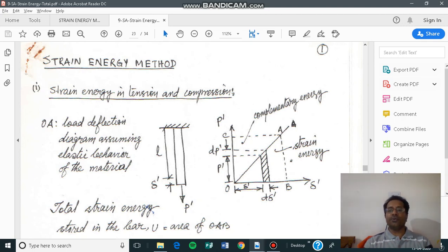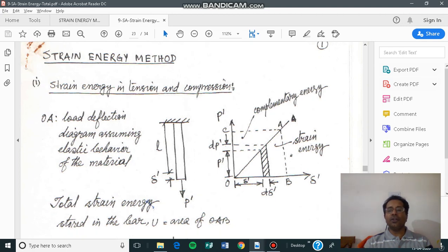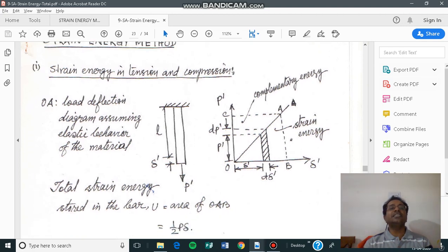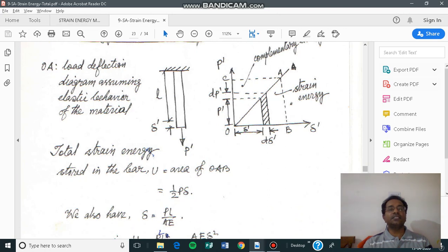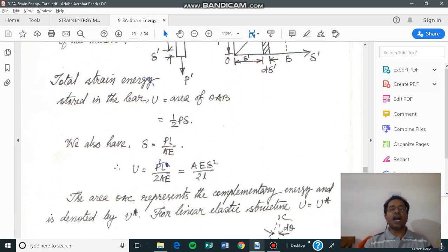If the internal force is a direct load, axial load, we all know, or if you don't know also, these expressions with figures will help you to understand how you can calculate this energy from the axial load, that is P squared L by 2AE. Each line is self-explanatory, so I will not take much time to explain in detail.